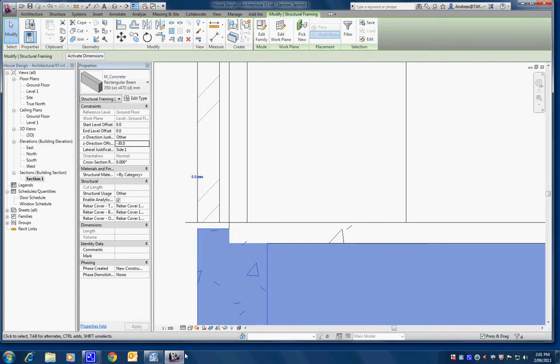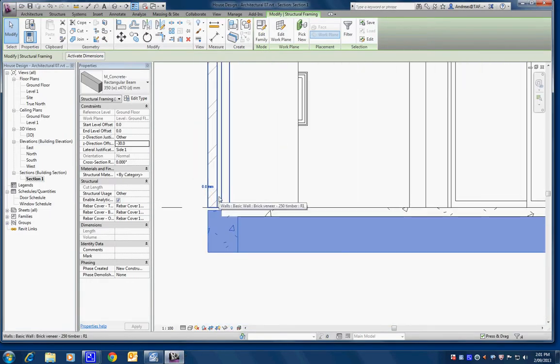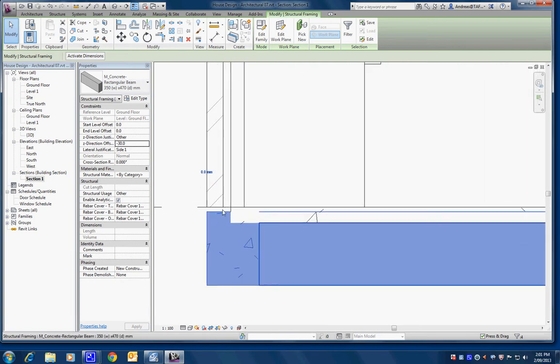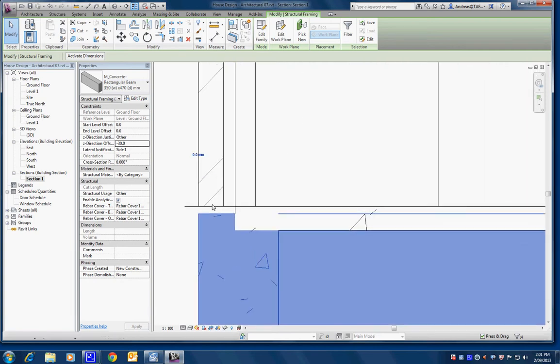Okay, we're going to move on and see if we can do some modifications here. Look at this thing here. We're going to drop that down. It's the 30mm gap, but we're only going to drop it down to 20. Basically it's a workaround for when we do our structural floor plan. If they're touching, we will have problems putting a thicker line around the outside of our floor plan. So it's just a workaround to not let it touch, and we'll go only 20 down.